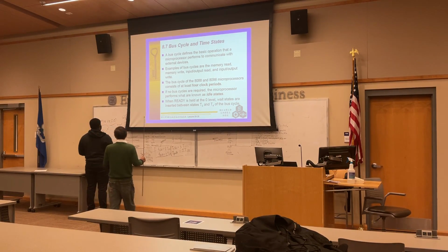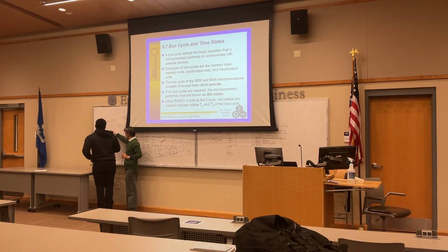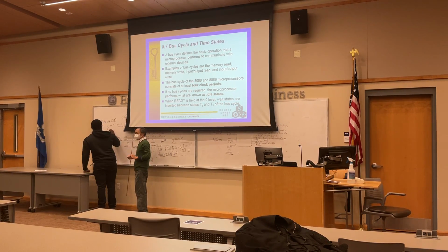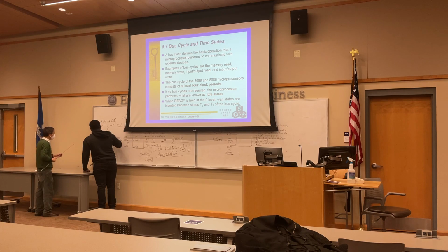We are reading a memory, right? Reading memory. So memory read bar should be enabled. Read bar 1 or 0? Should be a 0. And we are not writing, we should disable it. Then we set it to 1. Yeah, we're not writing, so we should set it to 1. Disable it. Yeah, 1. And we are in the memory mode. Enable memory mode 0. And we are receiving data. So transmit receive bar.